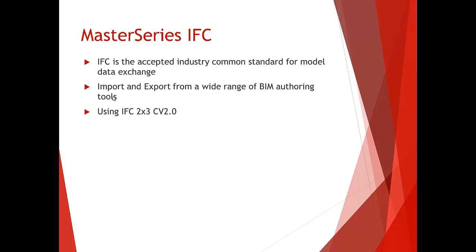We're using IFC 2.3 with Coordination View 2, which is pretty much what everyone uses. The Coordination View is basically a certain subset of the IFC, which makes it applicable to our types of applications, i.e. building structures and the likes. So this is what we're using, and indeed that's the common standard that all other software that deals with building modeling will use as well. So that's going to bring us in line with all of that.